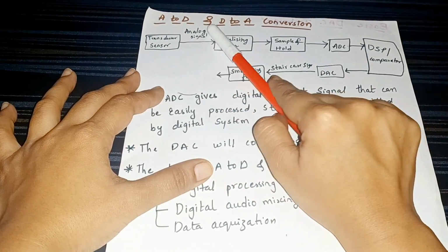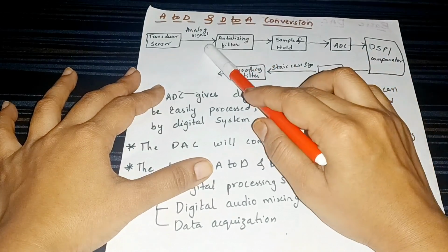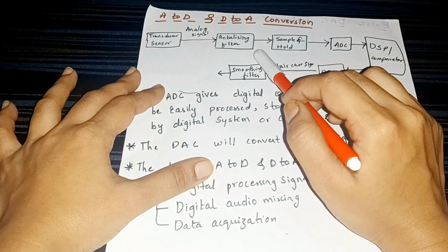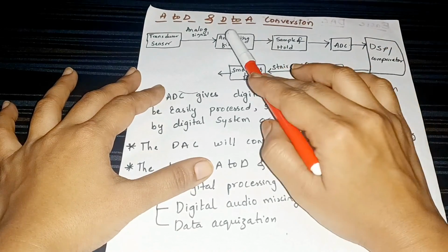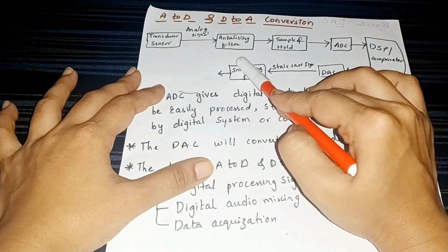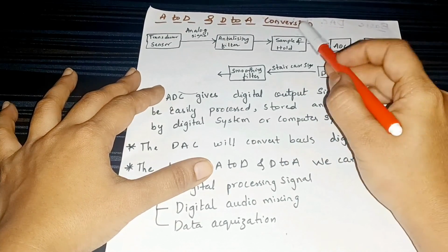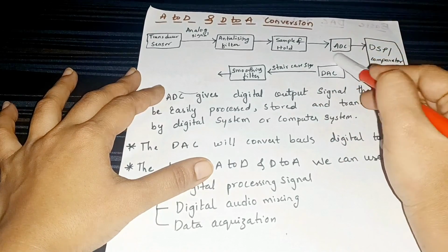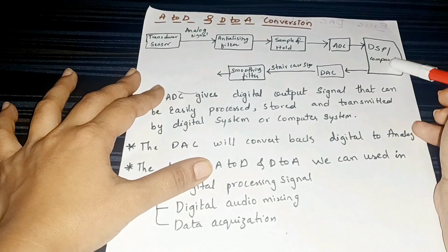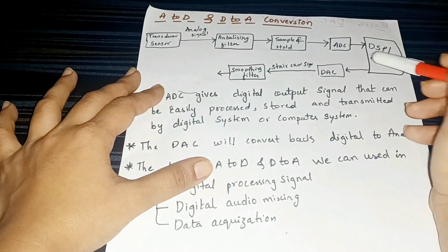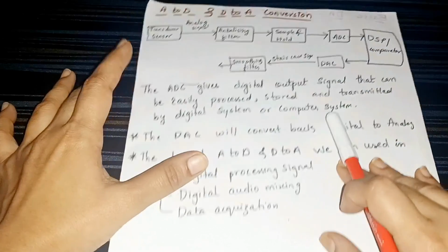If we give an analog signal, see what the waveform will be. We will have some wire impedance or noise distribution, so there will be some disturbance in the analog signal. Then we use a filter to remove all unwanted noise and wire impedance. Then we give it to a sample and hold, which connects to the analog to digital conversion, and the digital output we get can be converted back to analog by using smoothing filtering.